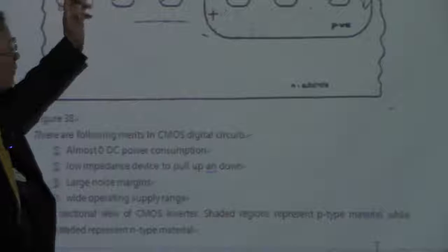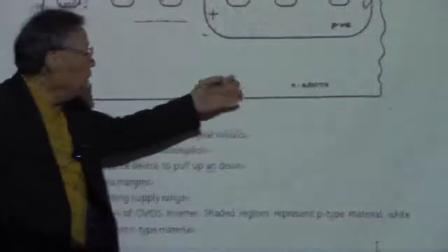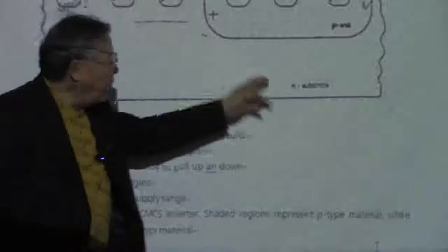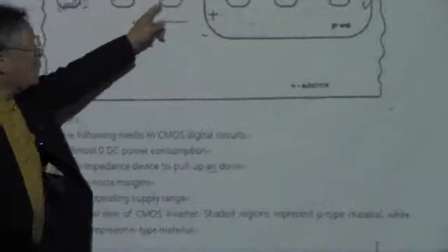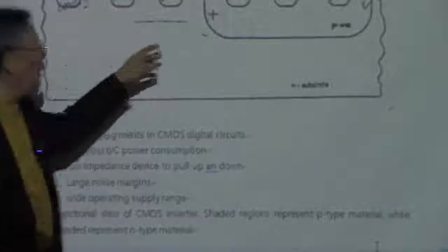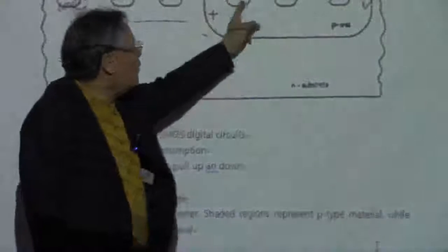But it is another story which CMOS is going to be taken. For example, do we have to use a P substrate or an N substrate? If you choose an N substrate, it means that you're going to build the PMOS in most of the substrate, and then locally you set a P well like this, and then you set the NMOS. So in this configuration, most of the device is made out of the PMOS, and then occasionally you are going to have an NMOS to make an inverter, to make a